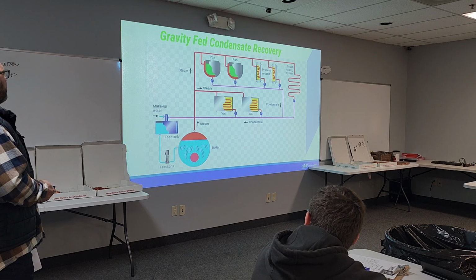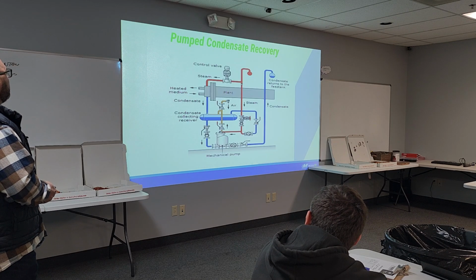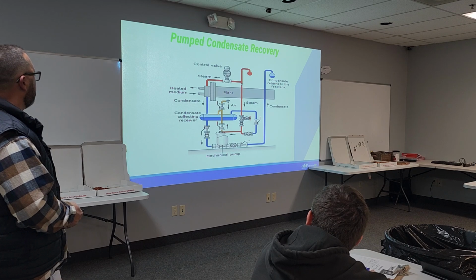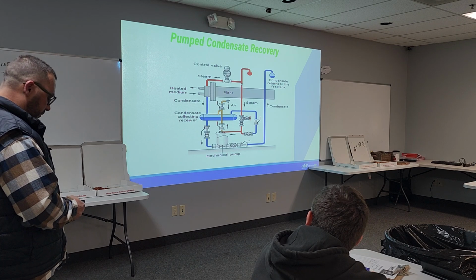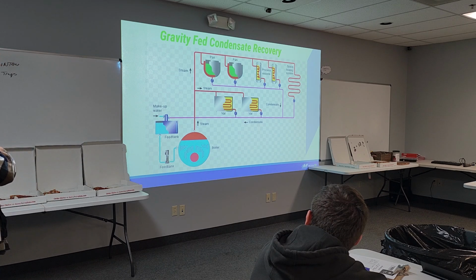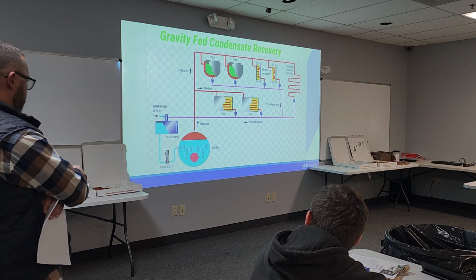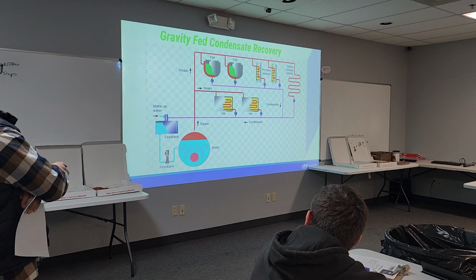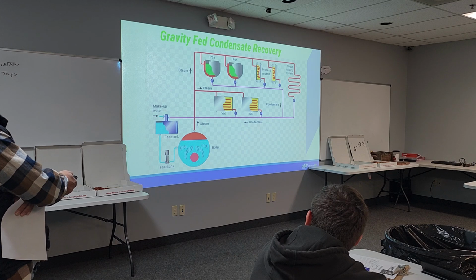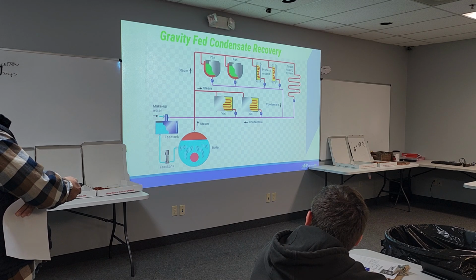So you can gravity feed condensate back, or you can pump it. Those are the two options, really. Can you go back a slide? Yes, sir. So notice we've got traps on pretty much every kettle there. Got some shell and tubes there.